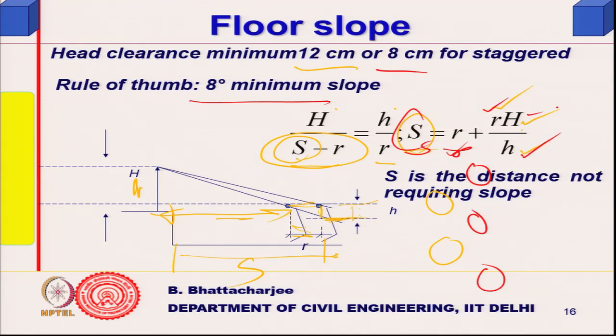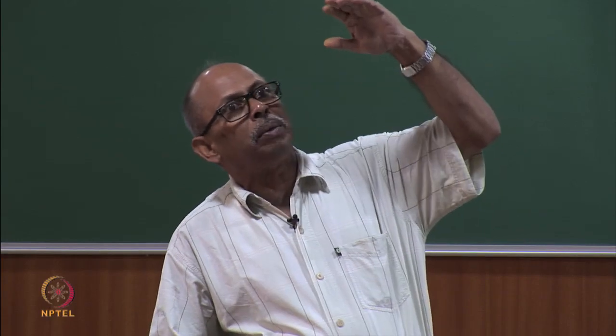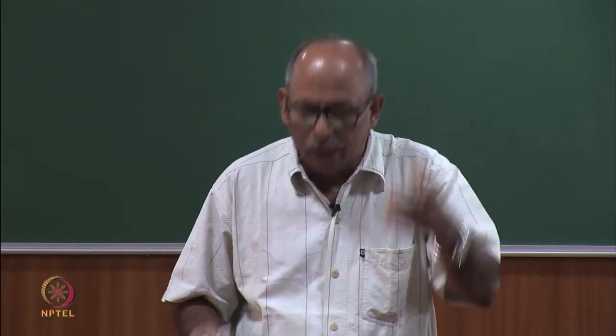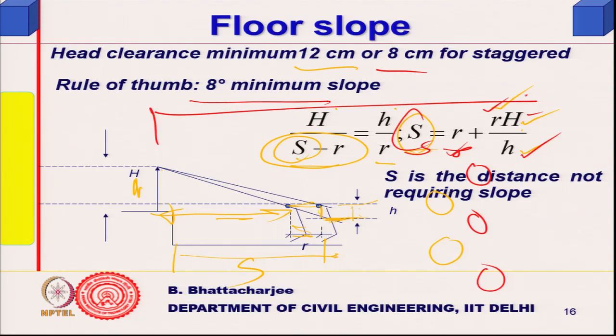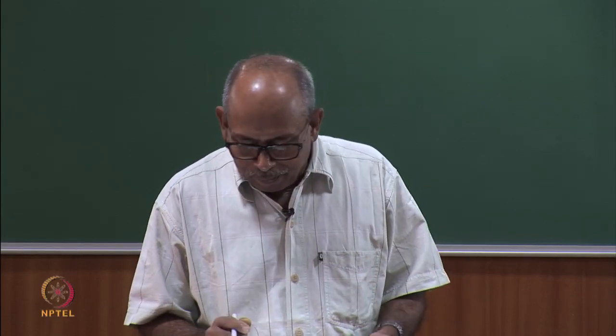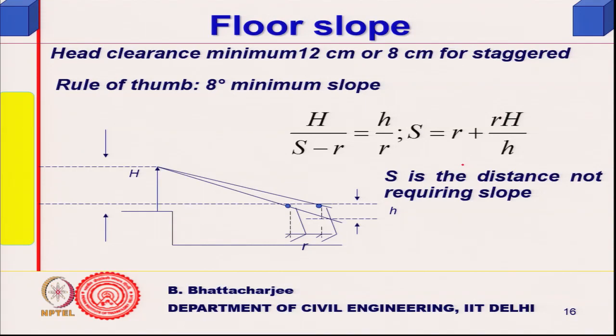R we are talking about, and height of the source would depend upon performance. Now, as I said, the other day I was saying they kept the speaker somewhere around 5 meter height. It is all ridiculous. Why do you need 5 meter? If you put it somewhere there, the sound will go somewhere there, unless you want to send the sound away. And it was also convex like this, which means the sound will go somewhere there. It is not going into the auditorium, it is actually misuse of the whole energy. You are not using the energy properly, no idea basically. So, this is not required. So, this is the formula, and we can actually calculate it out.